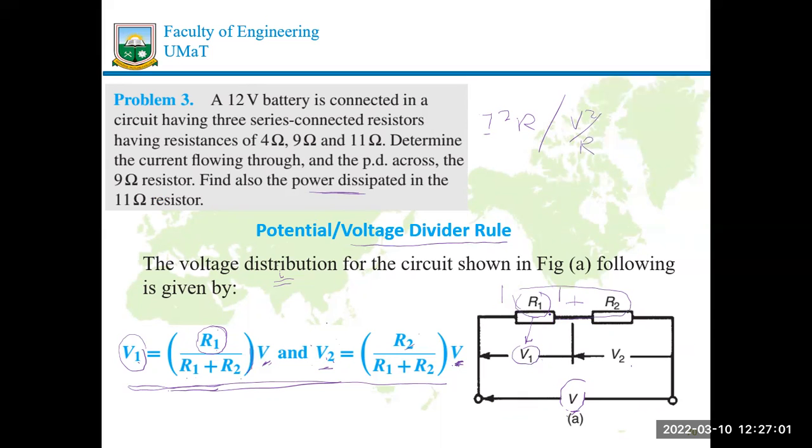So we normally have to multiply by the voltage across the set of resistors that are in series. Okay, one other thing that can be done is someone can give you V1. I can give you V1 is known. I can give you R1 is known. R2 is also known. Then I'll tell you to find V. You can use this formula to do that as well. Or I can give you V1, give you V, and give you R2, then ask you to find R1. Okay, so that is a way for which you can use this formula to compute for additional parameters that are not known.